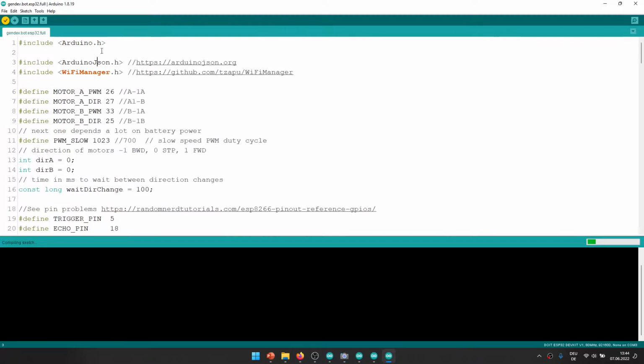And it also has this for easier configuration. It has a Wi-Fi manager on board. So what happens is that if it can't find a Wi-Fi that it can connect to, it will create its own Wi-Fi hotspot, and then we could configure it using that hotspot and give it the credentials of an existing Wi-Fi that it should connect to, which is quite advanced and taking a long time to compile, as we see.